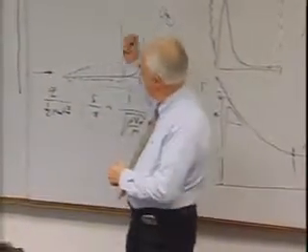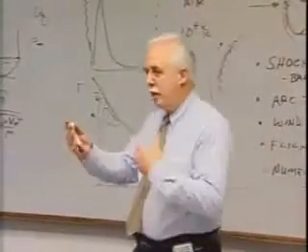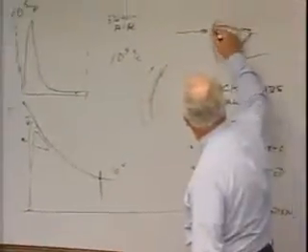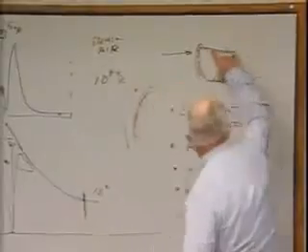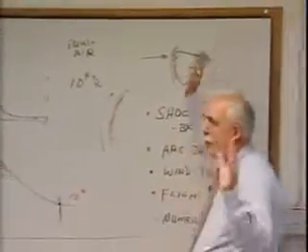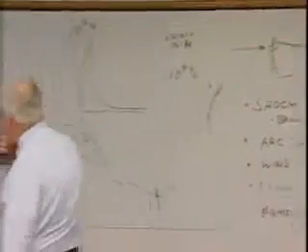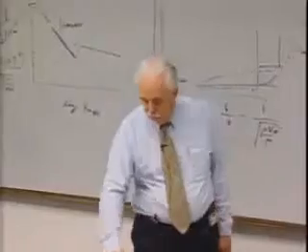We really didn't get the flow through. In fact, we eliminated the flow through because we had one-dimensional models and we wanted to understand the process in one dimension. But in flight, fortunately, we were a factor of 2 over just in that region. Over this region, I'll show you a chart, we were way over. And again, I'll try to address that. And again, the shuttle has really helped us in understanding the lee side flow.